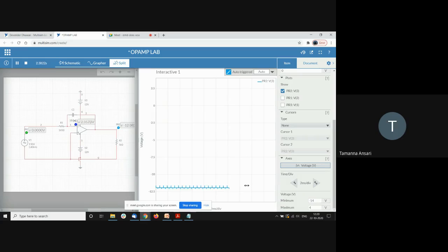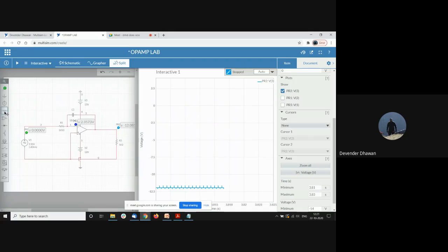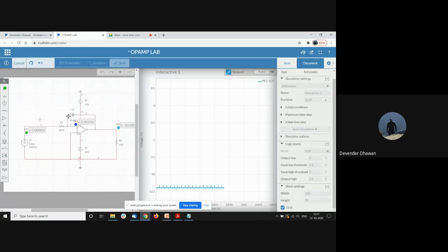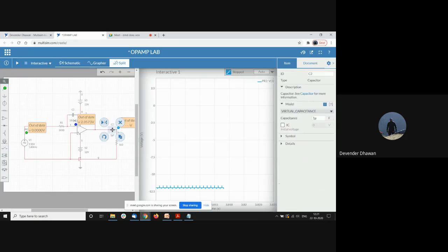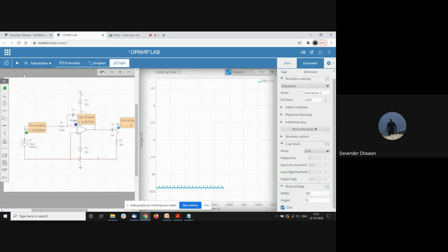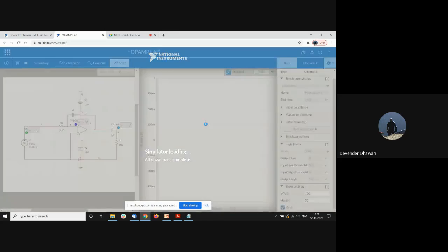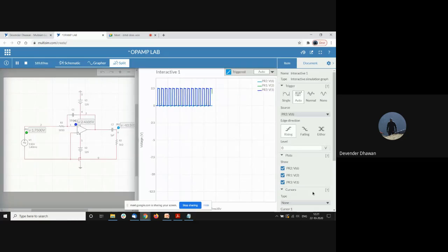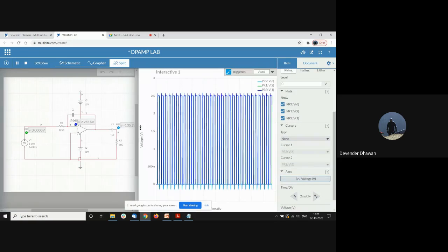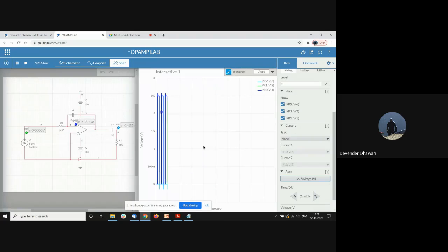Spikes only. I added that capacitor because right now you can see that it is at the -12 level. There is obviously some -12 DC offset here, which is because of this part only. To remove that, I added that particular capacitor. That capacitor has no effect here, because our feedback is anyway taken before that. So now you see our spike is also on the same scale. For that only I was adding this capacitor.